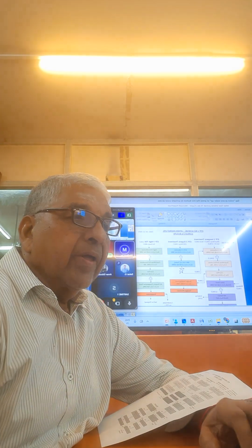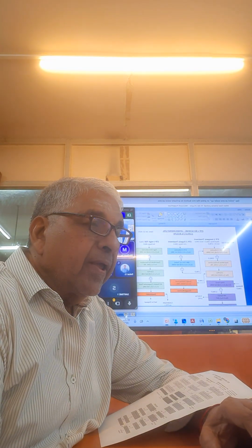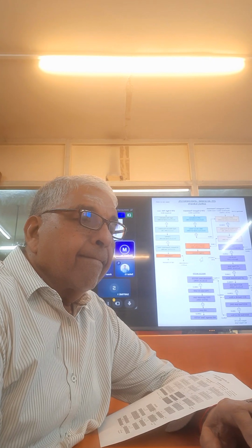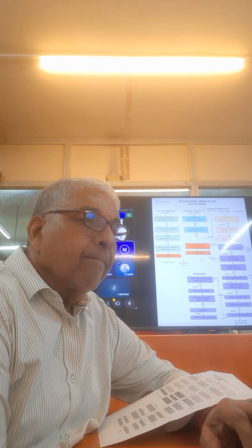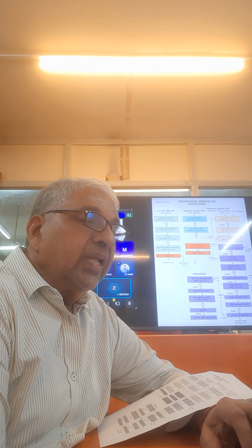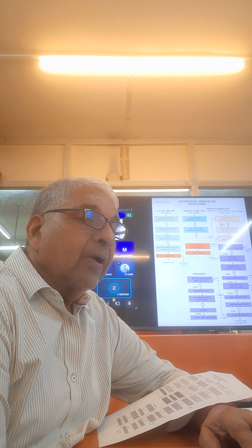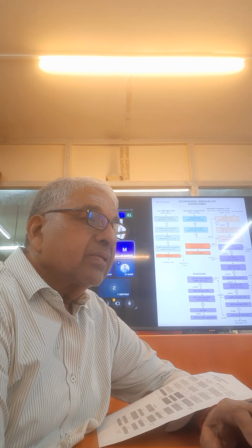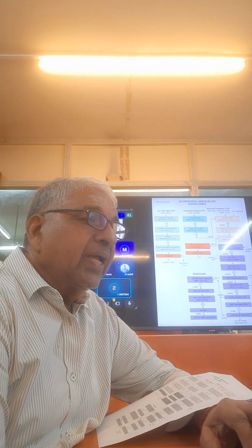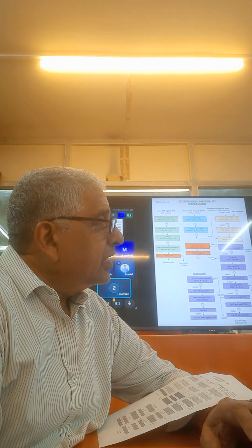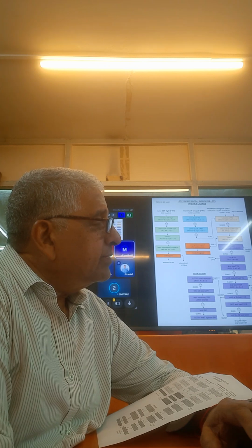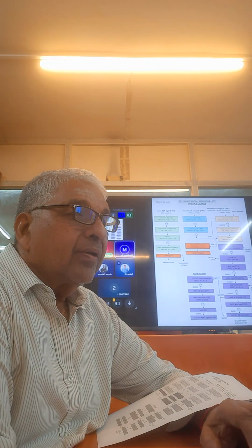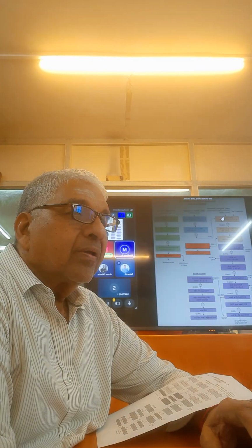Yeah, so you can add a decanter there. From the decanter, whatever the recovered water, will we be sending it back to the sludge sorting tank? No. That decanter water will go to the ETP1. So it will go to the collection tank. Yes, because it may contain some turbidity. So it will go to the ETP collection tank via drain.